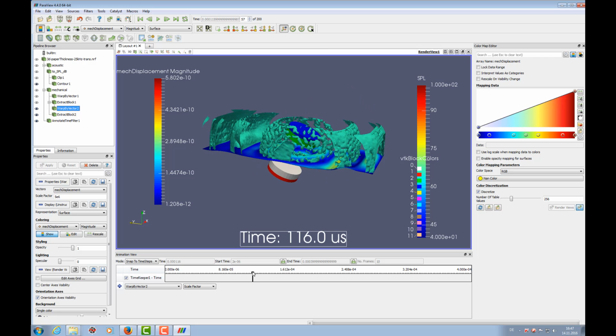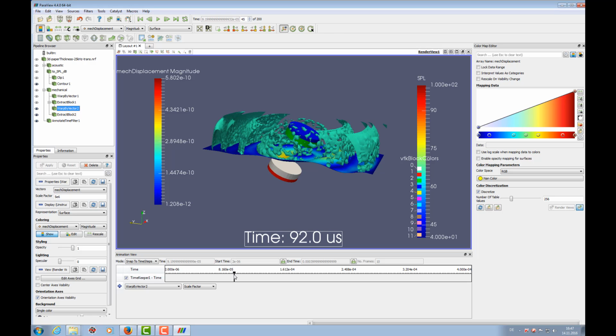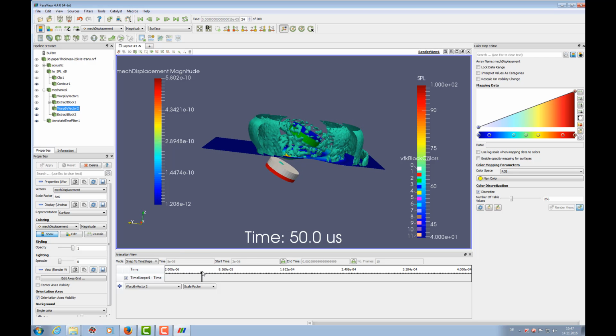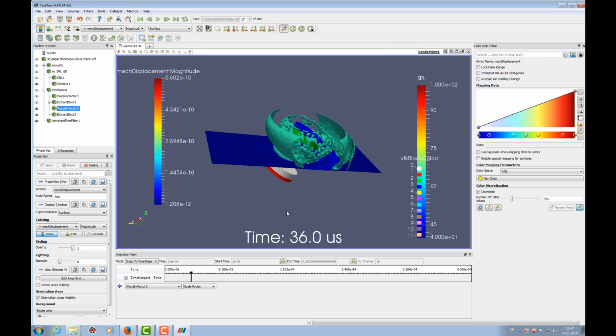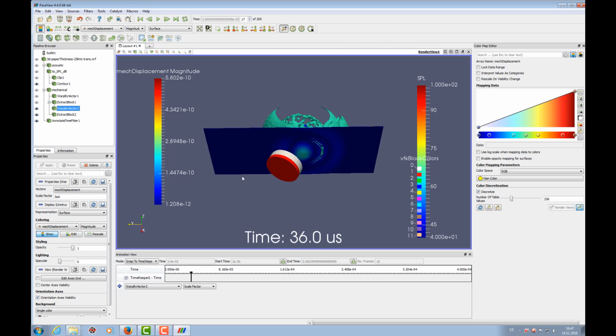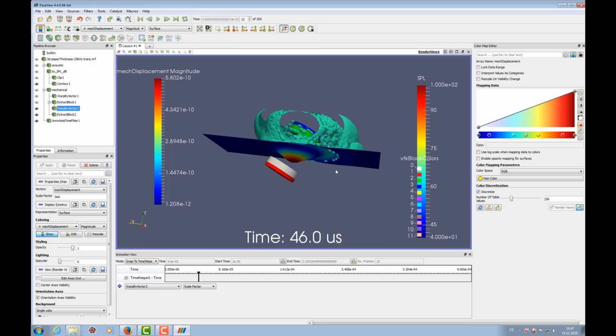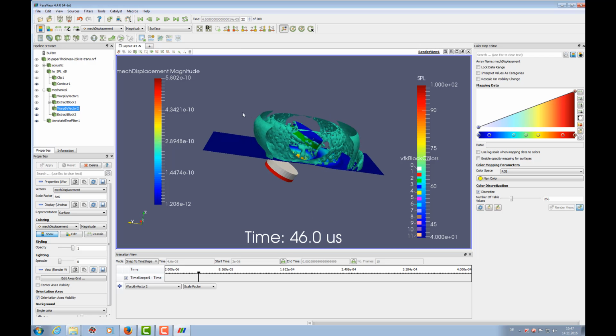So what we can see currently is that a wave is traveling from the transducer to the paper, and that wave is then launching an acoustic pulse on the other side as well, but this pulse is not visible. Why that? This is due to the double impedance shift, air to paper, paper to air.